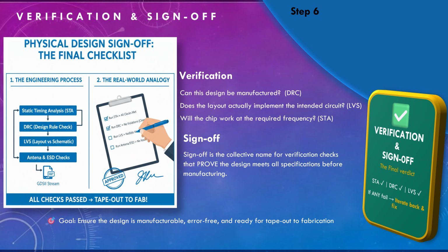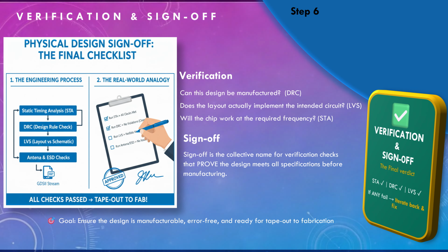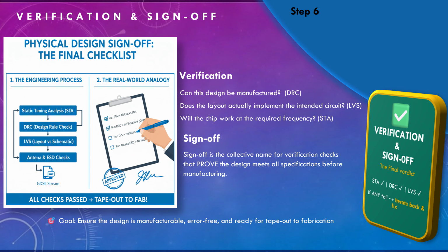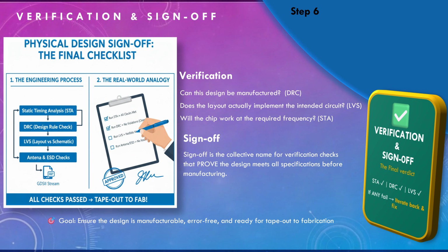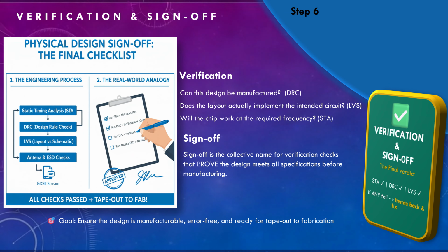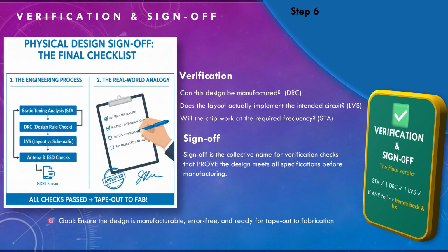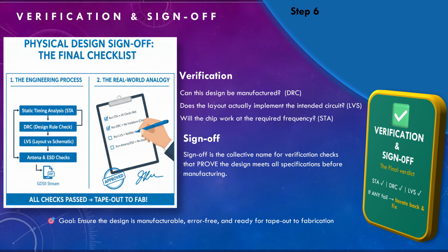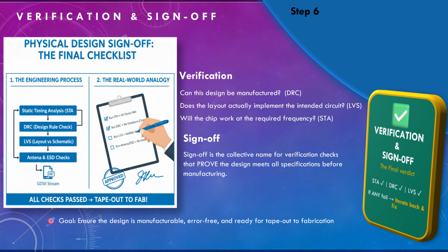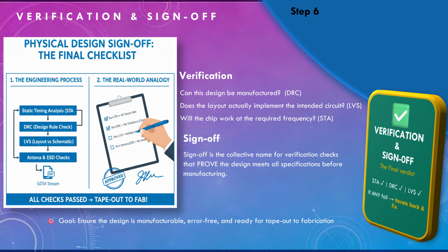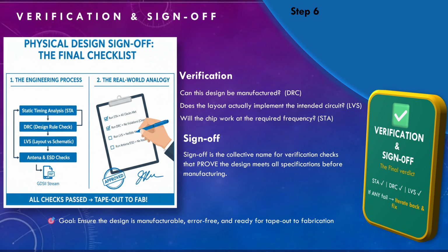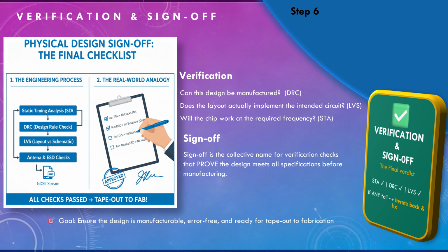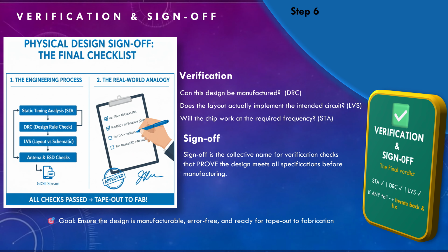Does your physical layout match the netlist? Every connection present? No shorts, no open circuits? STA, Static Timing Analysis, again, final timing check after all changes. Indian analogy like engineering college exam results. All 3 exams, DRC, LVS, STA, must all pass. Even if one fails, back to the drawing board. No backlogs allowed before graduation, tape out.